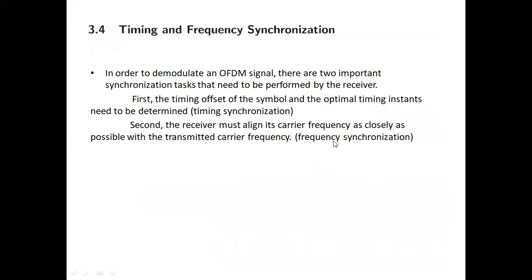So what can possibly go wrong? Whenever you go for OFDM, of course, OFDM is a tool for you to tackle fading. By now you might have an idea why we went for OFDM and why we took the IFFT. Because we wanted to convert the frequency selective channel into a frequency flat channel.